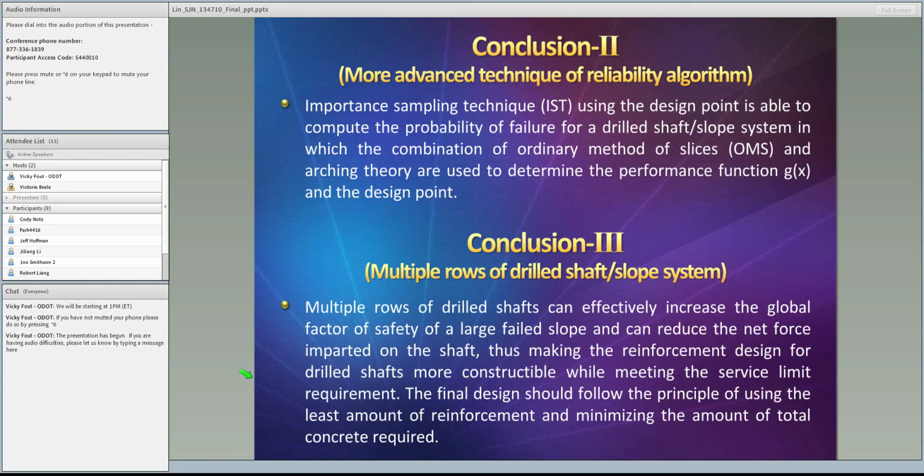So until now, the Ohio student project has all of these tasks done. As a recommendation for the implementation, first one is: in our illustrative example, the ATH 124 slope, the mean and variance of cohesion, friction angle, and unit weight are just chosen from Kulhawy's papers in 1999, and in future designs, we have to calculate them based on the measurement